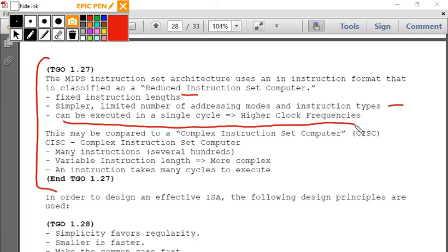If you wanted to in a complex instruction set computer, you could just have multiple types of instruction. You have a 32-bit instruction that adds 2 numbers, or you can add 5 more bits to get another register to add 3 numbers. And you could potentially require another ALU, which adds area, but potentially improves throughput because you can add 3 numbers together.